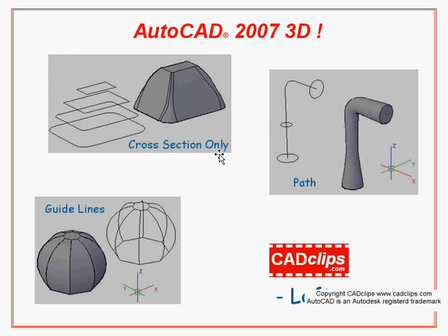With lofting with the cross section, all you have to do is provide lines that are closed, and in fact I don't even think they have to be closed, it'll close it for you, but you provide a series of lines that change elevation somehow and follow some sort of route. This is very uniform because I've tried to keep it simple, but with any sort of cross section, you provide the slices and then it will loft the new solid over those objects. So I've kept it fairly straightforward.